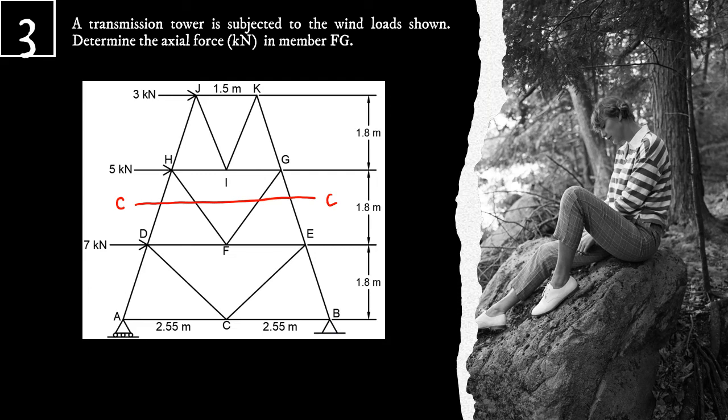Now we reveal the forces in the cut members. For unknown forces, we assume them to be in tension. So we have force DH, force FH, our interest force FG, and force EG. For force EG, we already solved its magnitude and direction. Its direction being compressive.